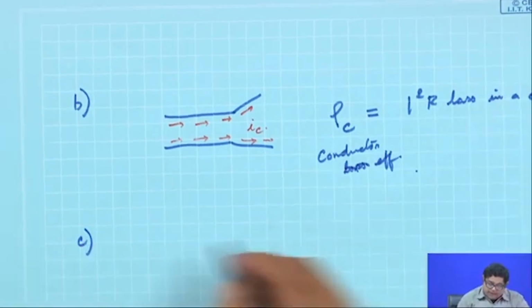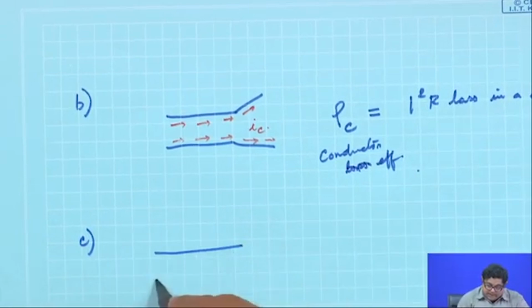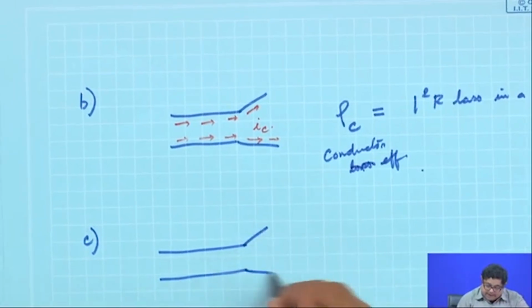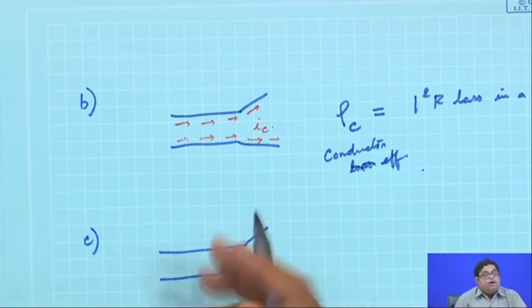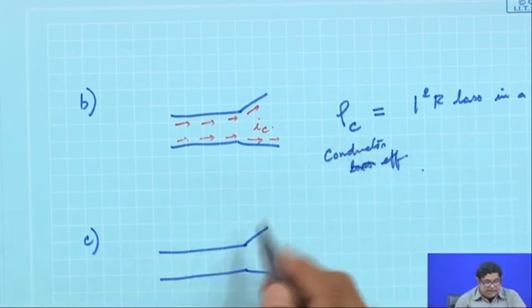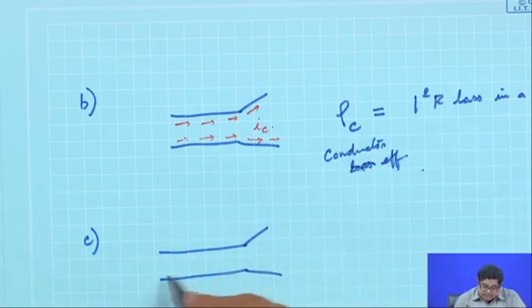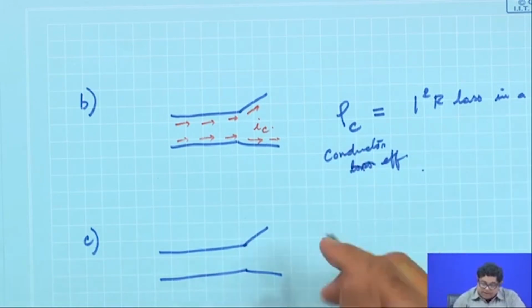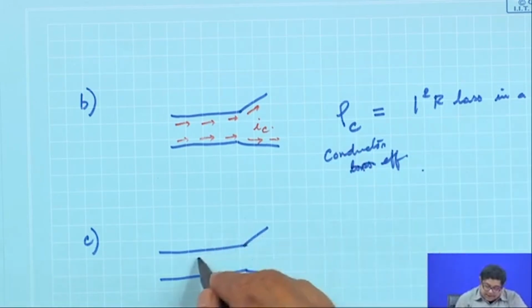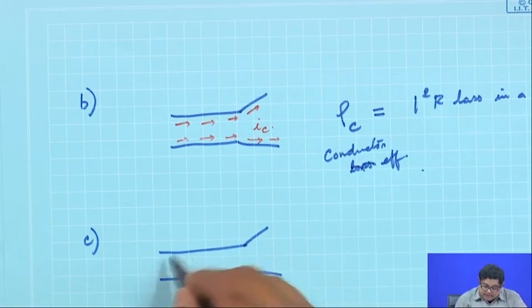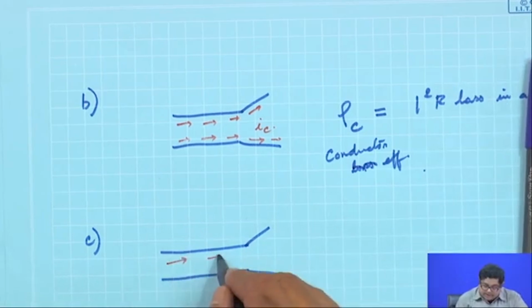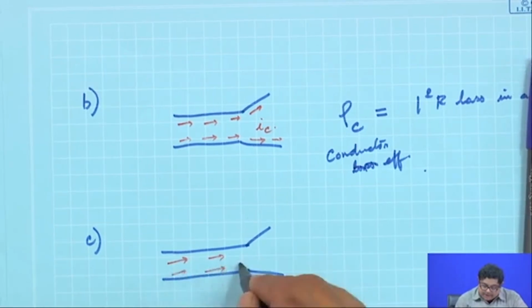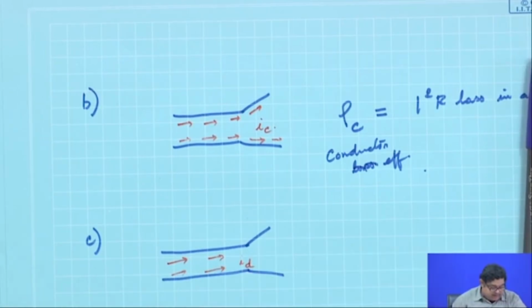Similarly, there will be power dissipation in the dielectrics. Even if nothing else is there, there is air dielectric, and in many antennas there are various dielectrics. There will be displacement current through them, which I can call the dielectric current I d.